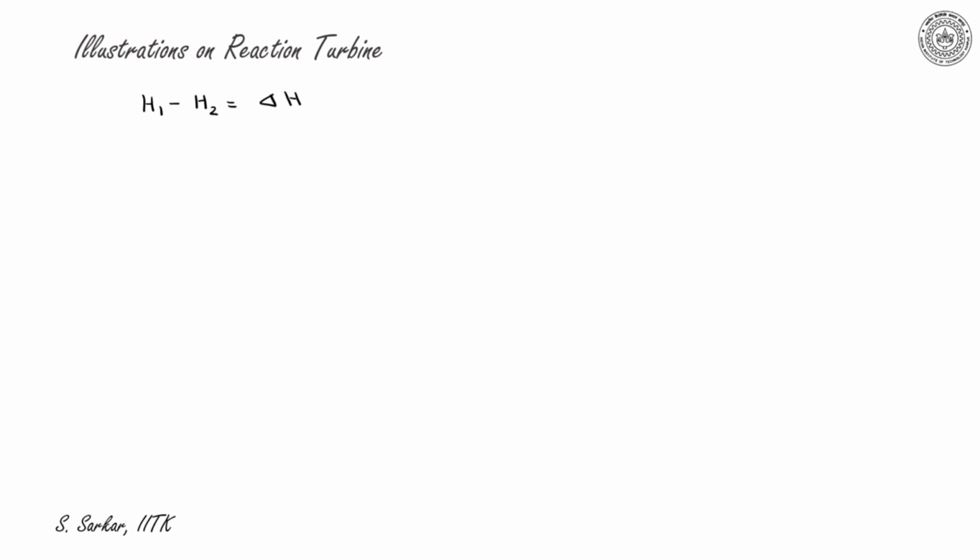This can be stated as the difference in static head between the inlet and exit of the turbine, designated as del H S, or this is del Z, the difference in elevation.